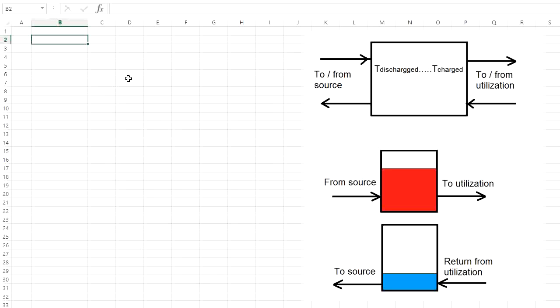In order to calculate the parameters of the storage systems, let's start with the boundary conditions, which is the heat source temperature, 95 degrees C. Then we will have the temperature difference in case there would be some intermediate heat exchangers between, let's say, the source and the tank fluid, or the tank and further on.